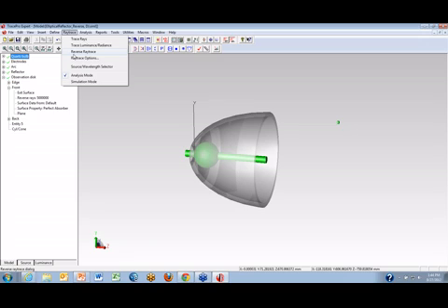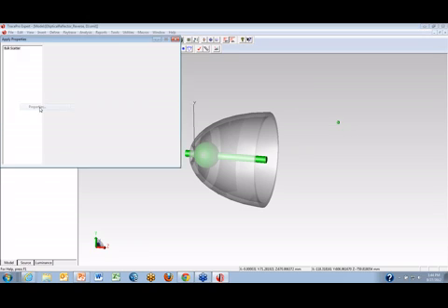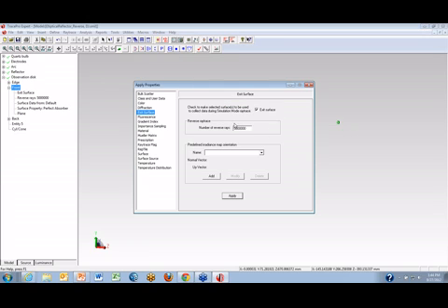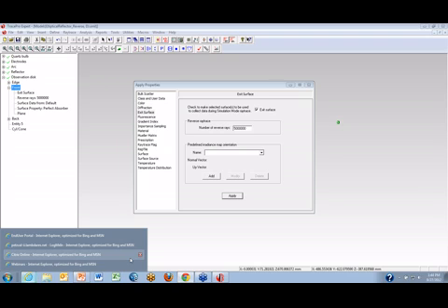Yeah. And by the way, if you haven't done reverse ray tracing before, this is where you would find that particular menu option in TracePro. And you would also see the reverse ray trace here would do that. You see where I've put up the 5 million rays. That would be using the apply properties and going to the exit surface where you would set that number of rays going in the reverse direction. So if you haven't done that before, try it out with maybe one of your systems. See how that works out for you. You need to make sure too with the reverse ray trace that your sources are surface sources. Reverse ray trace does not work with file or grid sources. So just one quick note there.